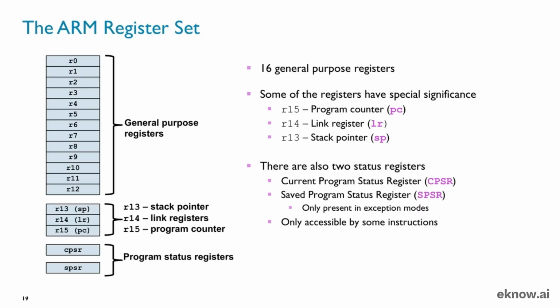Now, things get more interesting with the last three registers, R13, R14, and R15. While you can sometimes use them for general data, they each have a very important, special role assigned by convention, and in some cases, by the hardware itself. Let's start with R15, the program counter, or PC. This is perhaps the most critical register.